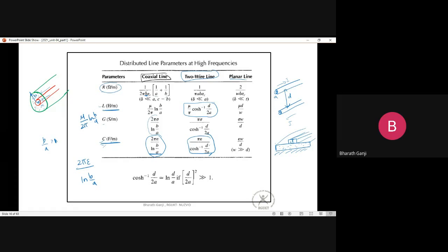And what I can see is these parameters, and particularly inductance and capacitance, if the material properties do not change with frequency, you usually have a situation where L and C do not change with frequency, but they basically depend upon the geometry of your wire. What kind of geometry do the wires you took have? What is the distance between the wires, what is the dielectric medium between them, what is the diameter of the wires? These values depend on these properties. So say for any given wire I have these values. Let's suppose I have these values.